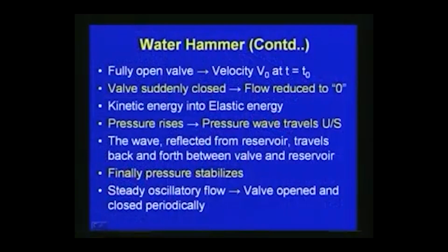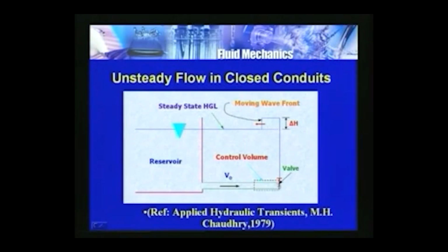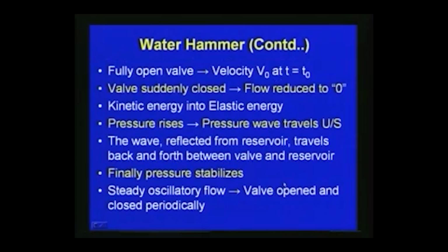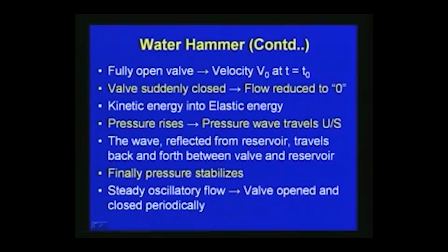Here we assume that for the fully open valve the velocity is V0 at time t = t0, and then the valve is suddenly closed, so the flow is reduced to 0. With respect to the movement of the fluid there is kinetic energy. Due to the sudden closure this kinetic energy is transformed into elastic energy, the pressure rises, and a pressure wave travels upstream.